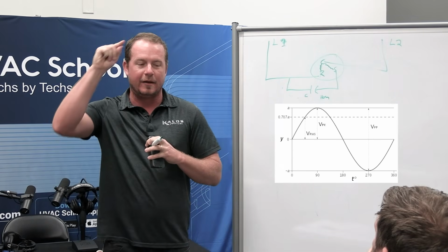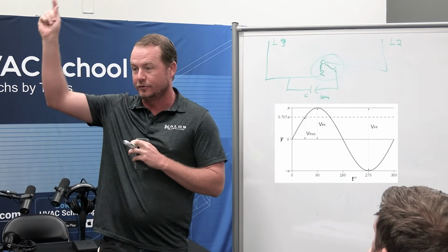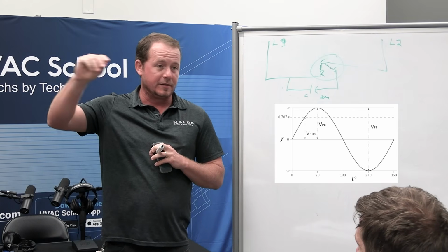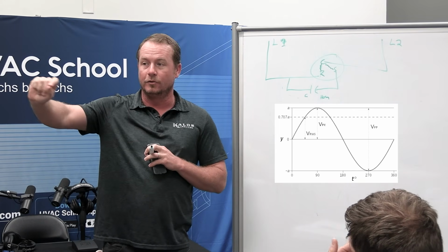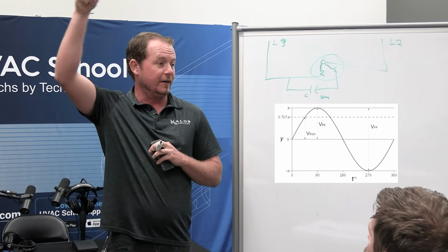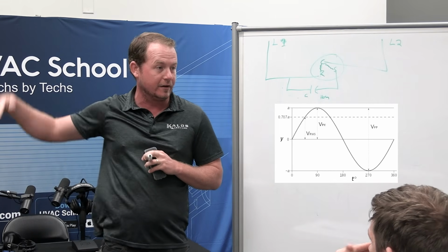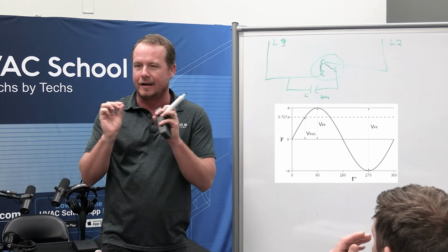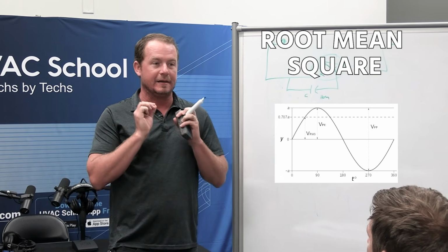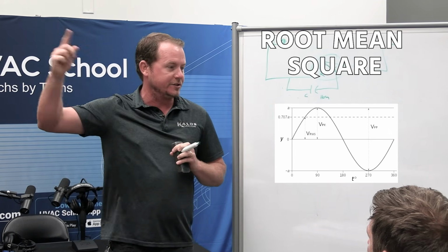So as that sine wave, as the voltage changes, because in alternating current we have this constantly changing voltage, right? Everybody buy that? If I measure with an oscilloscope, it's going to actually show the voltage changing on that outlet on the wall. It's not going to always be 120 volts. It's going to be going anywhere from about 150 volts down to 0, and it's just going to keep doing that over and over and over again, right? So when we measure a voltage, we're just kind of measuring an average. It's something we call RMS, root mean square, which is basically a mathematical way of saying what is the average of all these voltages that keep changing.